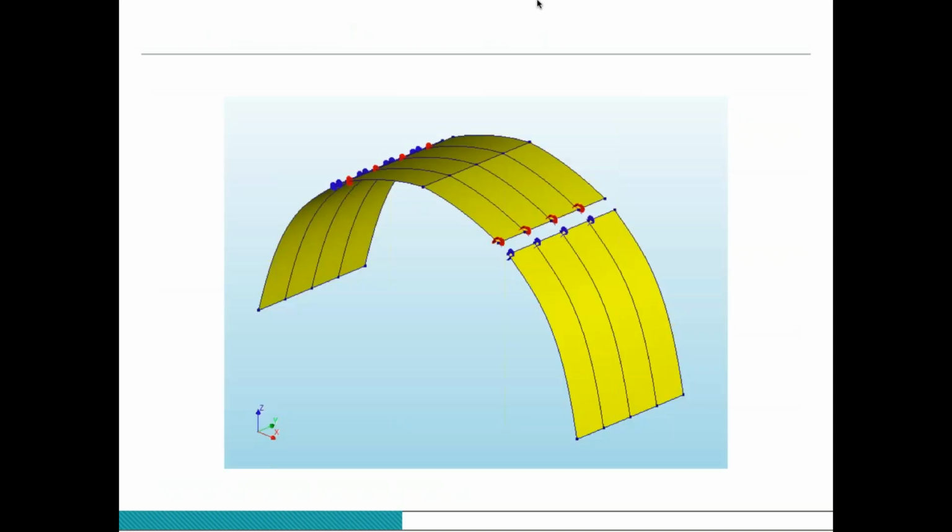Here is the way that I have modeled the tunnel segment. It's a part of the top of the tunnel. The tunnel is about 60 meters by 80 meters. Each of these 3D curved plates is 1 meter in elongation, and the nodal springs are applied at a distance of 1 meter.